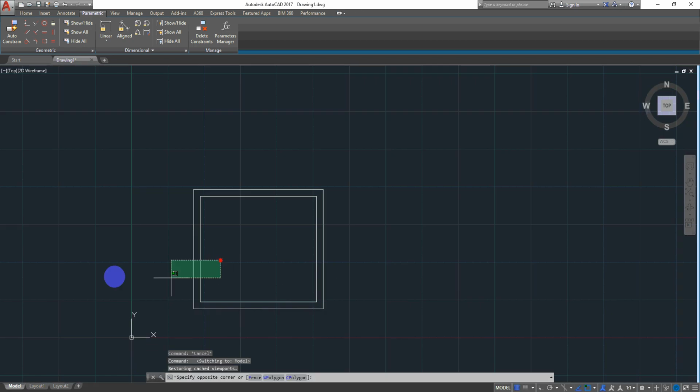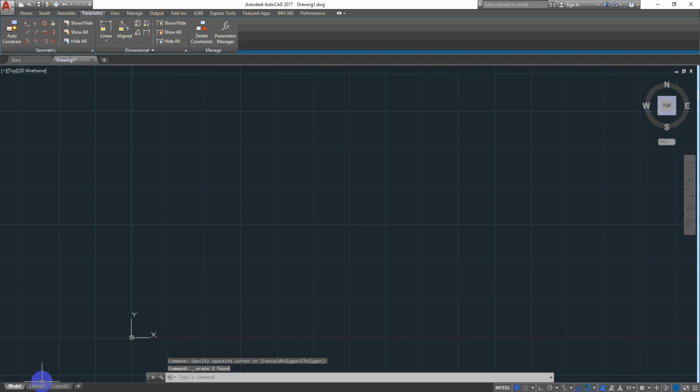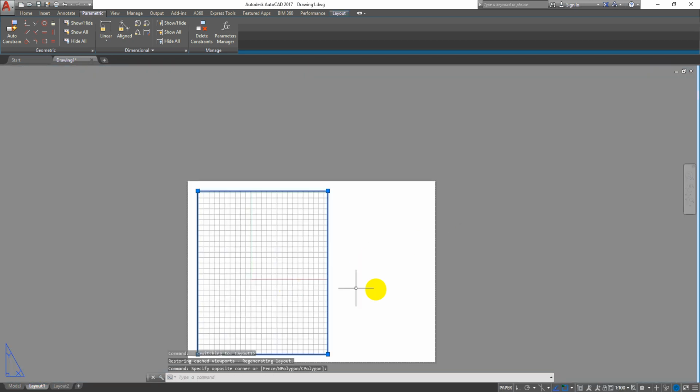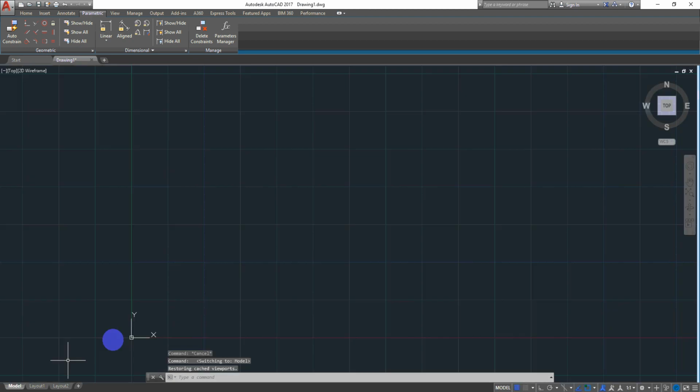Okay, so as I mentioned before, I think I have told in the previous chapter, somewhere in the previous chapter I believe. So if you are having a drawing, you should be having minimum 2 DWG files for that. That is because the model elements and the annotation elements. So annotation elements is what we are putting in this sheet file. So this sheet file should be having this drawing coming in as an XREF, not directly drawn like this here. So what I mean to say is that this is now our layout, and this layout has been set for A2 size, and I will be having a drawing here which is an external reference.